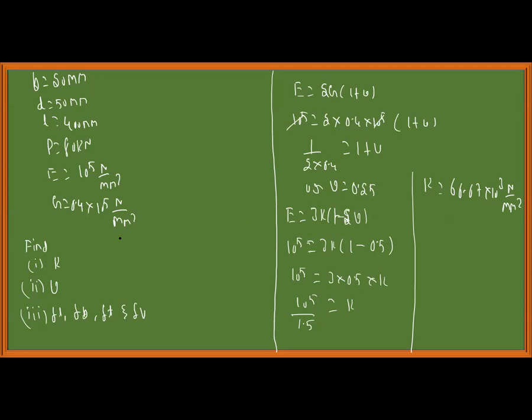This is the first unknown we have found. Poisson's ratio also we have found. Nu and K. Delta L we should find. Let me find the lateral strain. Linear: sigma is equal to Young's modulus times epsilon. Sigma I can find. Sigma is equal to P by A, which is equal to 80 into 10 power 3